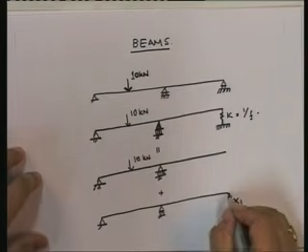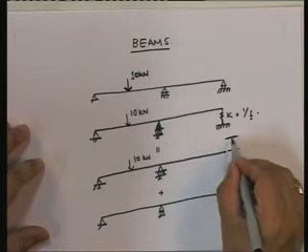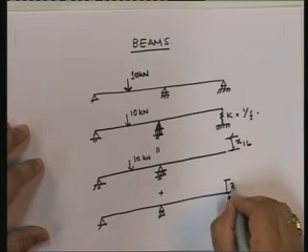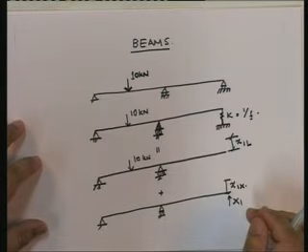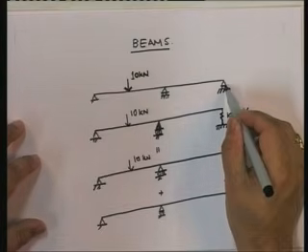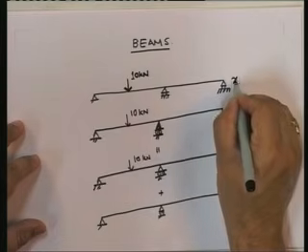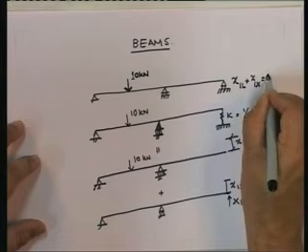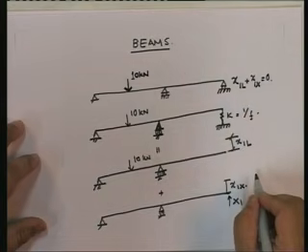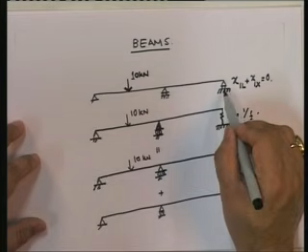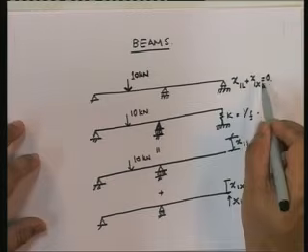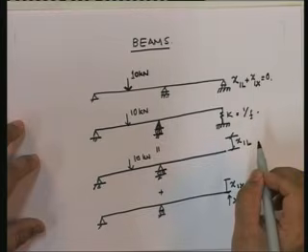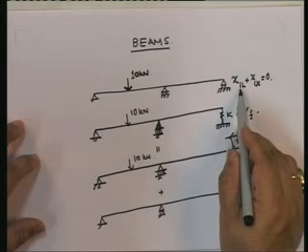How is the entire thing going to be different? The difference is that, note that here we computed x1L, if you remember, this is the x1 due to load, then we computed x1x, remember that, and in the last case we took the compatibility condition as x1L plus x1x is equal to 0, because in the real original structure, what was the displacement? 0. However, when you have a flexible support, what happens? Okay, this is no longer true.